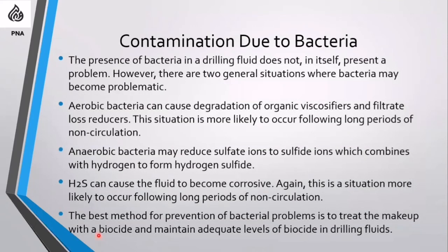We also have contamination due to bacteria. The presence of bacteria in a drilling fluid does not in itself present a problem. Bacteria in itself is not a problem for our drilling fluids. But there are two general situations where bacteria may become problematic. Aerobic bacteria can cause degradation of organic viscosifiers and filtrate loss reducers. This situation is more likely to occur following long periods of non-circulation.